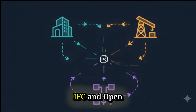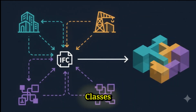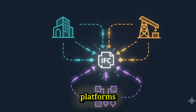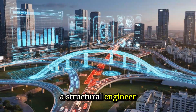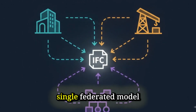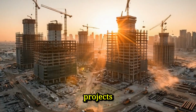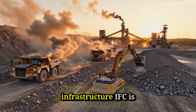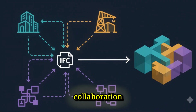Use case 3, IFC and Open BIM standards. IFC, Industry Foundation Classes, is the open file format that allows BIM models to be exchanged between different software platforms without data loss. An architect working in Revit, a structural engineer in Tekla, a contractor in ArchiCAD. Through IFC, they share a single federated model regardless of which software each team uses. For East African projects, where teams often work across different software environments with limited IT infrastructure, IFC is not a technical detail. It is the practical foundation of collaboration.